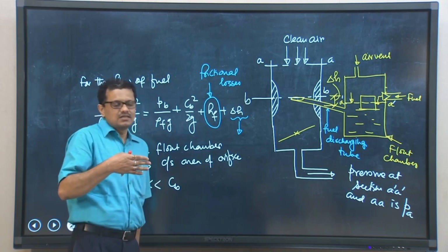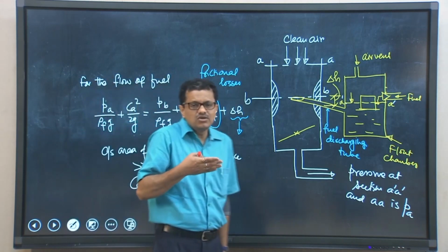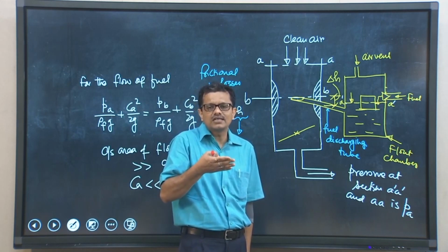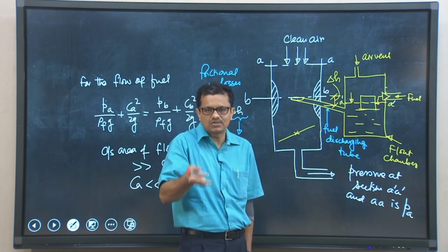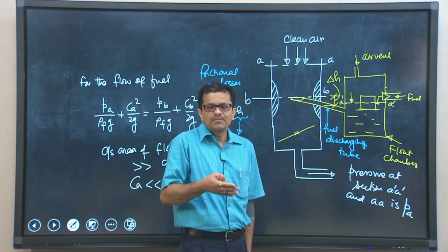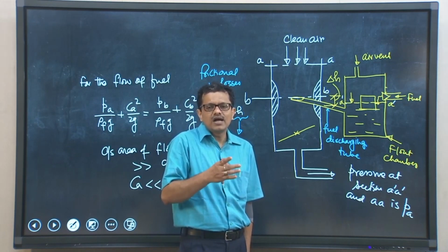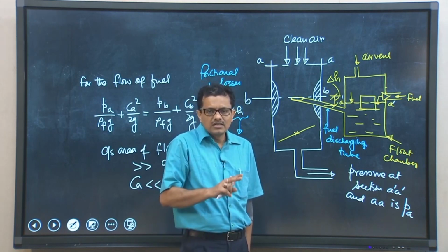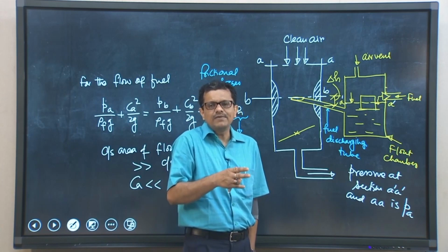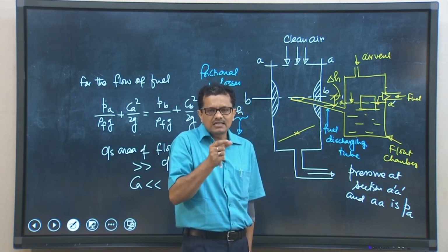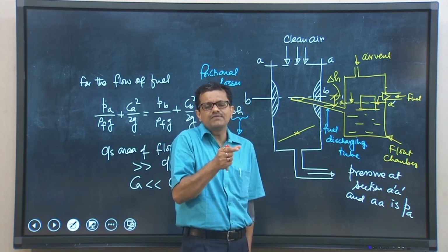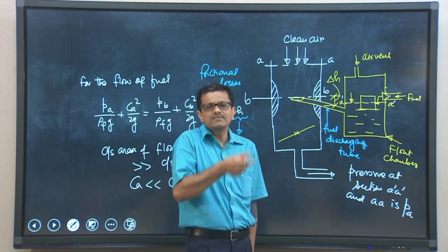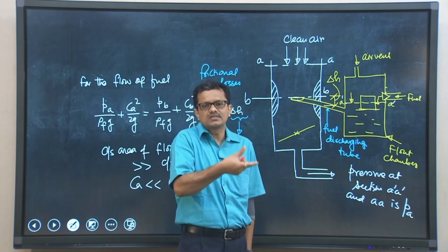Also, if it is a 2 stroke engine, we had seen that a 4 stroke engine has only one intake stroke vis-a-vis 3 different other strokes. But for the 2 stroke engine, it is one intake versus one other stroke. So, for the periodic filling, even if it is a single cylinder engine, the time gap between 2 consecutive intake strokes is very less, and we can approximate the flow of air to be almost steady.